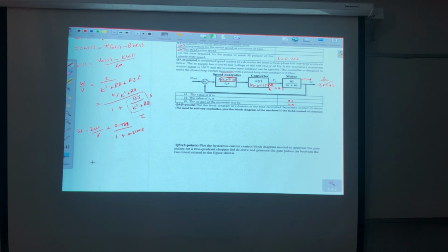So now the block diagram will be reduced to be what? Here I'm having a certain gain K I need to specify, and I know tau 1, which is 0.1 s. And this one I know, which is the 4.5. And this one we already have, which is the 2, correct? And this is a negative feedback. Yes?